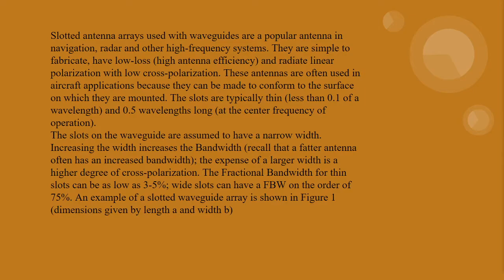So, these antennas are often used in aircraft applications because they can be made to conform to the surface on which they are mounted. The slots are typically thin, less than 0.1 of a wavelength, and 0.5 wavelengths long at the center frequency of operation.